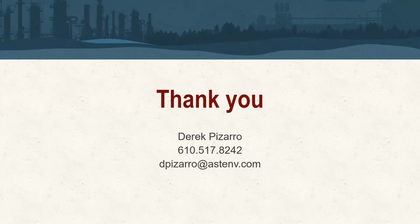The calcium polysulfide being a solution is going to distribute very easily through several injection methods, but from a treatment capacity standpoint, it's significantly lower than the Mackinawite structured iron. From a residency standpoint, it's just like any other solution you inject, right? Depending on your groundwater velocity, that's going to dictate your residency time.